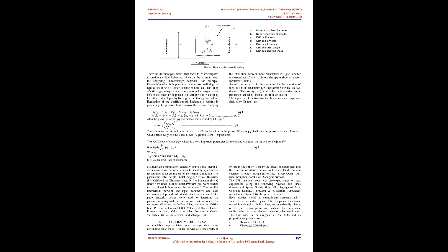Based on the certification agency's requirement, all the undercarriages are validated through testing, drop test, strength test, fatigue test, etc. Undercarriage testing is an expensive process and iterative in nature to arrive at the final design of shock absorber to ensure smooth and slow extension/rebound of landing gear for improved comfort of crew and passengers in the aircraft. In this paper, an attempt is made to present the interactions between the parameters during continuous fluid flow to help us understand undercarriage shock absorber design performance.